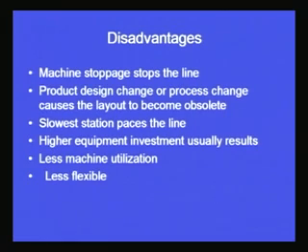Those are certain remedies that I have told, but the limitation is that the slowest station or the slowest machine or the slowest processing unit will dictate the speed of the line, or it paces the line. Then highest equipment investment usually results. So the equipment investment is higher.